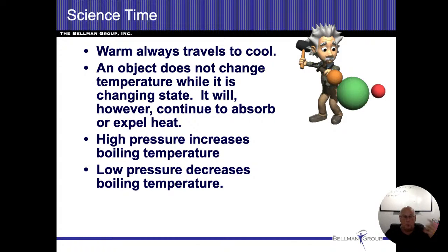Same thing happens with liquids and solids. So if I take a glass of ice water, and I'm in a 75-degree room, then that heat is going to be absorbed into the ice water. The ice water will be 32 degrees. That's the freezing point of water. So as it keeps absorbing BTUs, it's going to be melting all of that ice until the water is completely water and all the ice is gone. Once all the ice is gone, then the water will start increasing in temperature until it equalizes with the room.